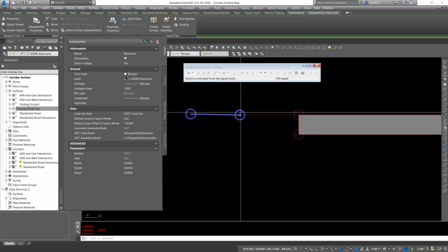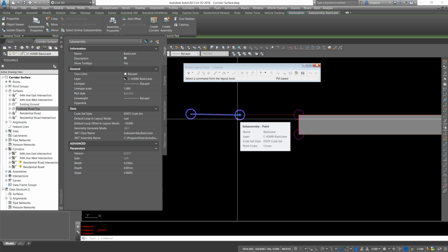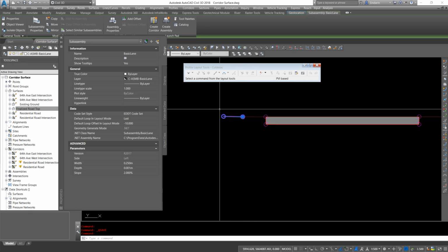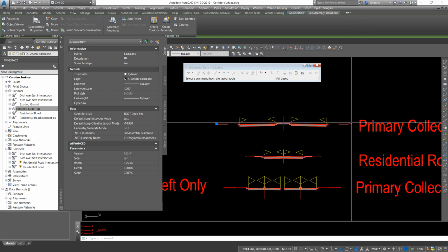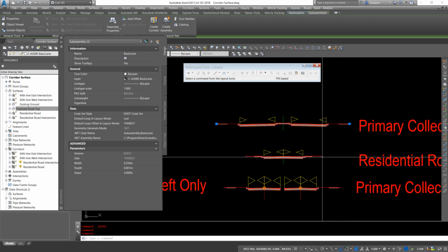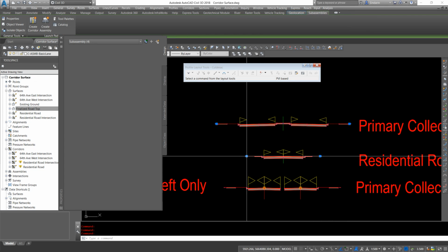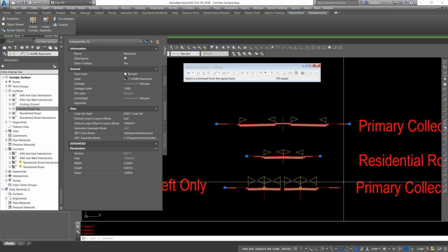If this piece isn't here, you can try snapping to lines. It might not work. You might not get the surface information. So I've just thrown a little 0.25 meter wide lane on the ends of all of my assemblies. So every outer piece of my assembly where there's a sidewalk has this added to it.